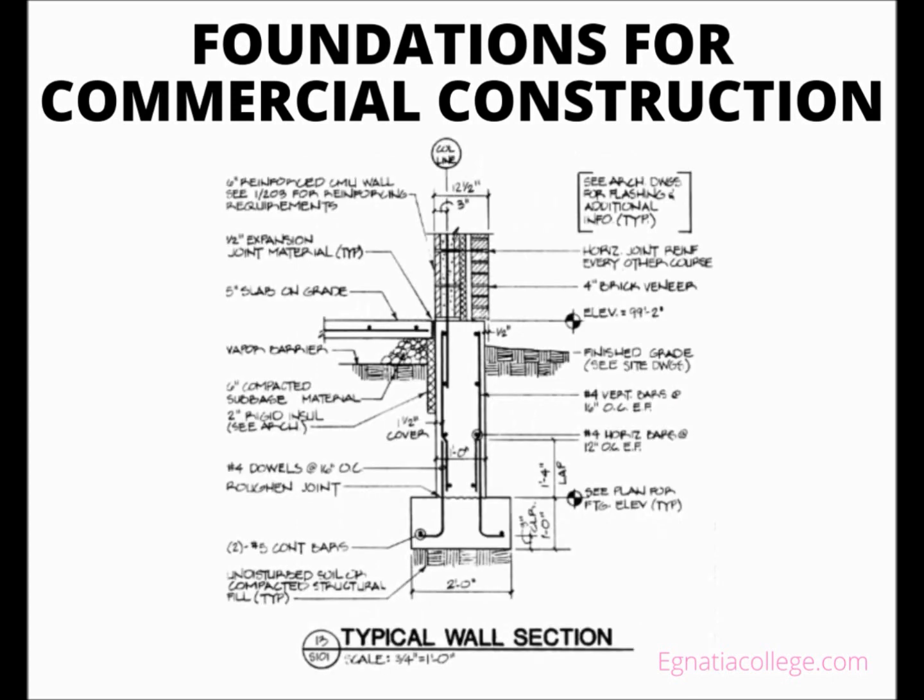The overall layout of the foundation is shown on a foundation plan. The dimensions and the reinforcement of the footings and walls are planned by engineers to carry the necessary loads. So it is likely that there will be several detailed drawings to further describe the foundation systems at different points in the building. Some of the reinforcement may be bars that protrude only a short distance out of the footing and into the wall. Reinforcing bars used in this way are called dowels and are used to keep the wall from shifting on the footing.